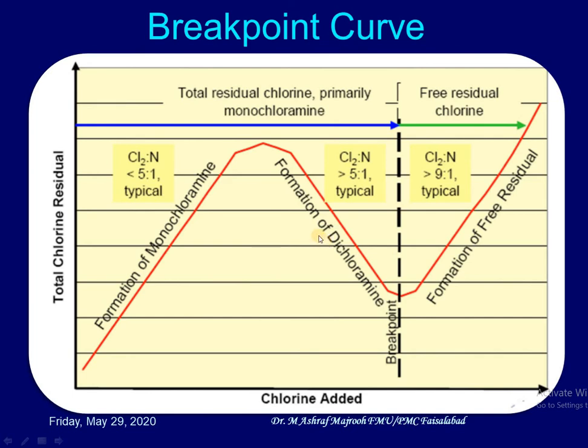of dichloramines, and then again the chlorine starts rising, but at this point of time the curve will not fall down and there will be free appearance of free residual chlorine. So this is the breakpoint chlorination point.